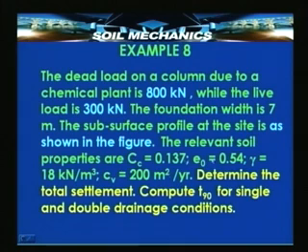The soil properties which are important from the point of view of consolidation are all known. For example, the compression index is known as 0.137. Obviously, it is determined for the compressible soil with the help of an oedometer test. You will see a soil profile shortly. Samples were extracted from the compressible layer of that soil profile and tested in the oedometer to get the compression index. The compression index, the initial void ratio of the soil, the unit weight, and the compressibility parameter CV are all known.